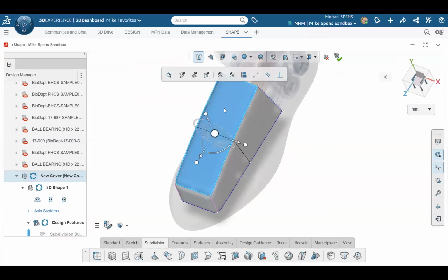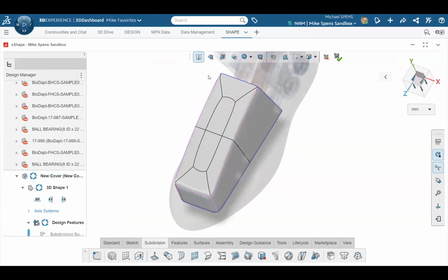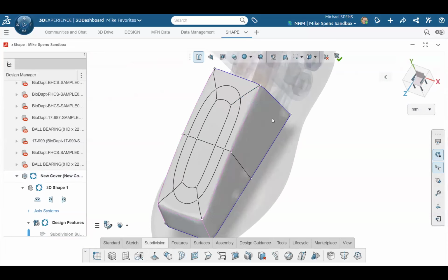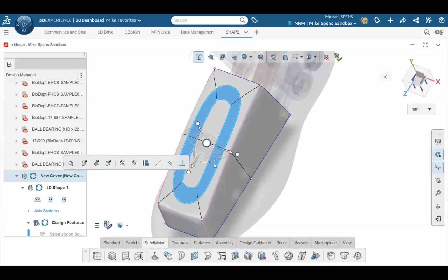So I'm just going to take this and subdivide these faces. Now, when you do a subdivision on a face, it kind of makes a racetrack. Don't have a better phrase than that. And let's also take these, since it's kind of a loop, and do one more division there. So this crease tool is pretty cool. It's not just for outside edges, but it's also for the shape of the subdivisions.